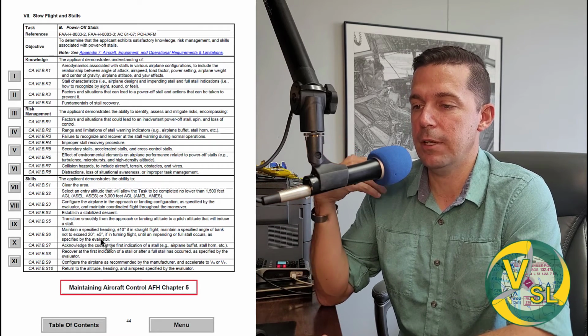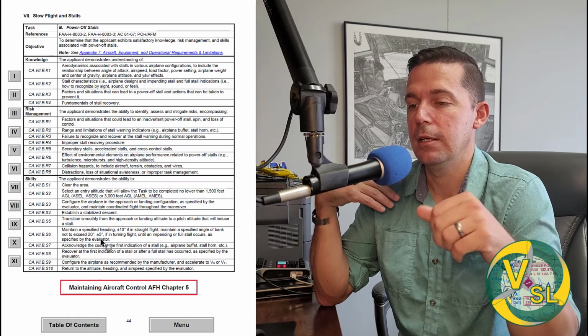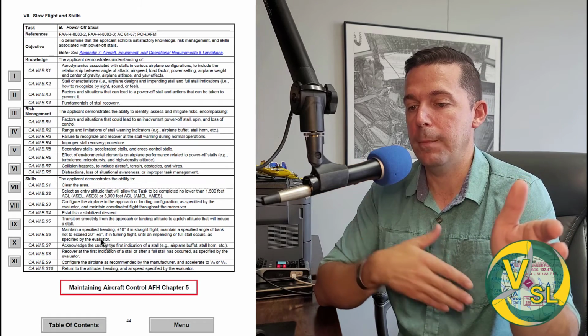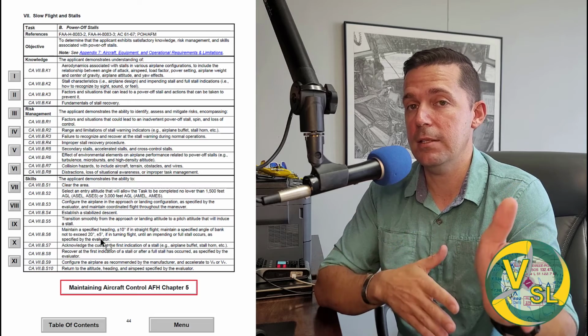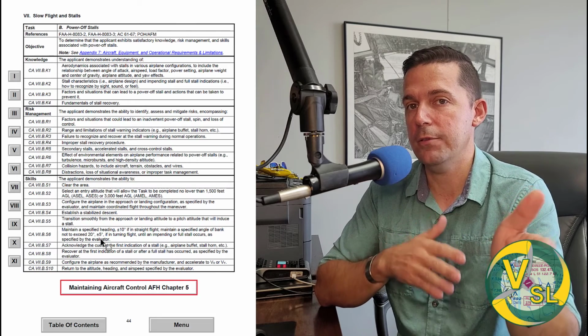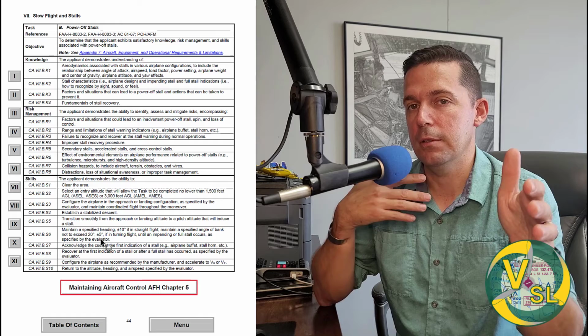A lot of times us evaluators will say, hey, pretend that road down there is the runway. I want you to turn base to that runway. And while you're turning base, I want you to induce a power off stall and recover. It's kind of a standard